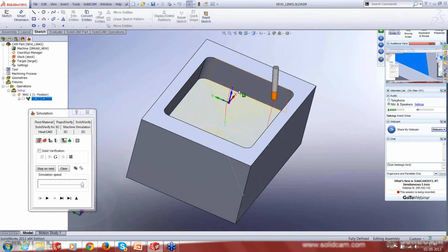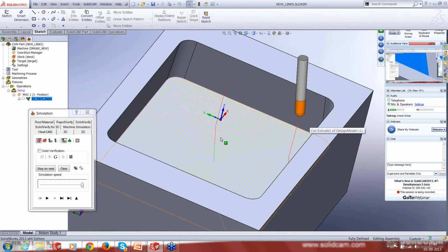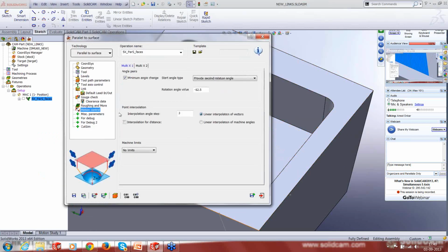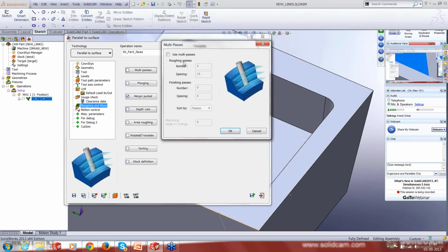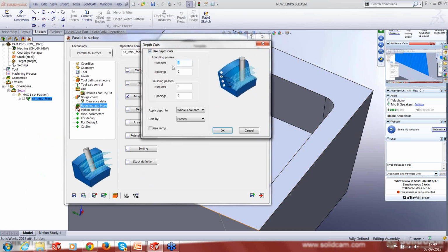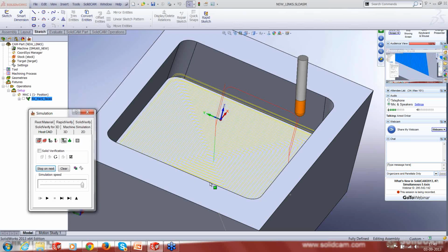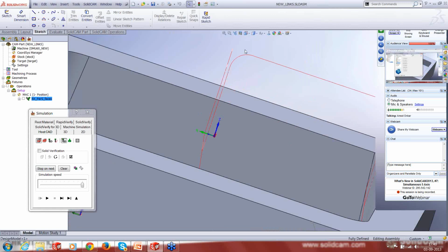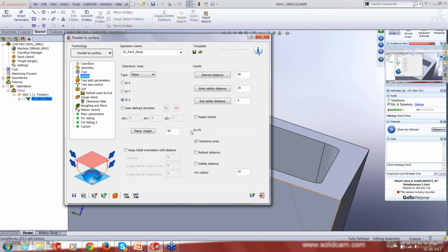The other function that we just talked about was putting up the arcs for rapid moves. So if I now apply a depth cut, or let's use a depth cut, 2 and 10. Okay, let's save and calculate. So we have now a depth cut. And you can see that we now have the arc fit in the rapid move. Where is this found? This is found in the levels page, and we have fit an arc out here.